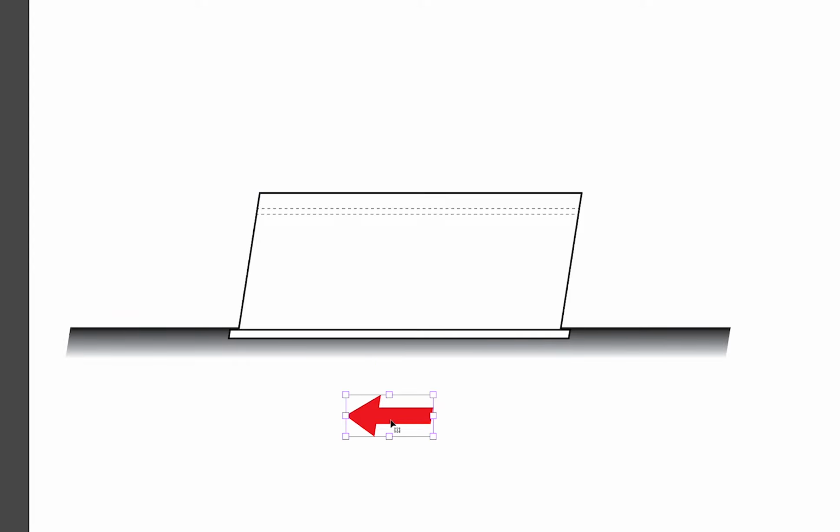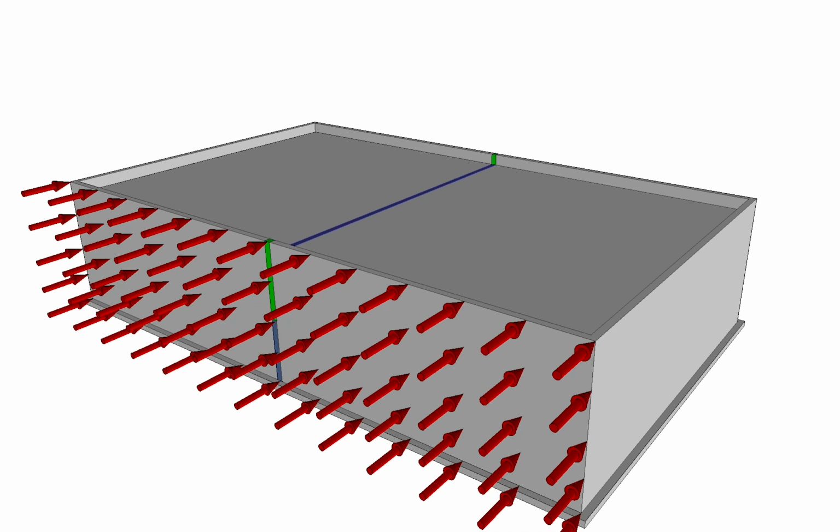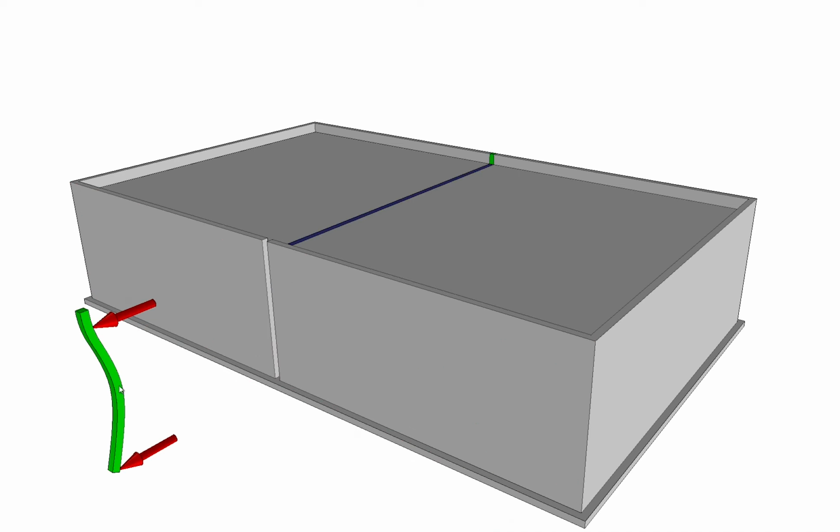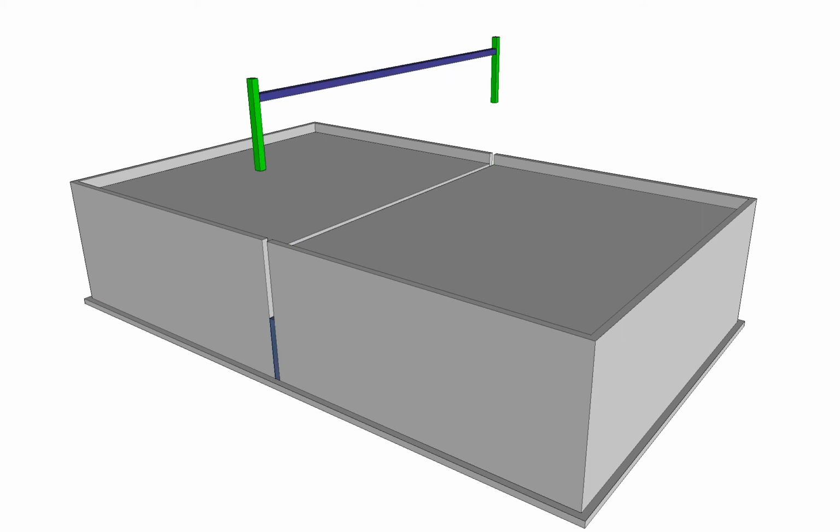Okay, this would be similar to a ground movement from the right-hand side of the screen to the left, and that displaces the foundation. So the wall element is spanning across here in the same way that it is for wind. It's attached to the ground here, and it's attached to the roof. So effectively, that wall is leaning on the roof structure. And so that gives us, again, the same kind of behavioral condition here where the wall spans from the foundation to the roof, but what generates it is actually the structural self-weight, a portion of that structural self-weight.